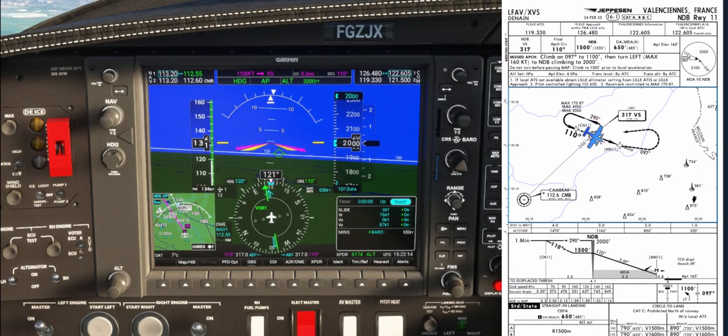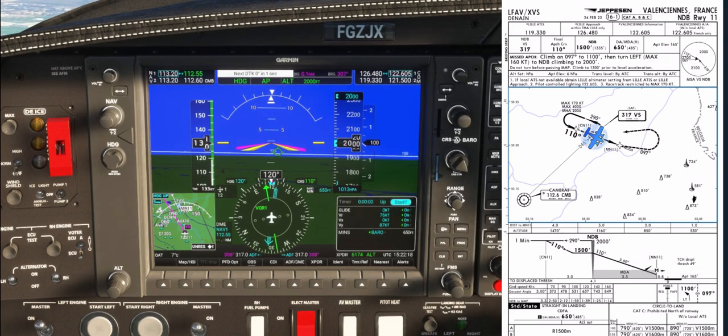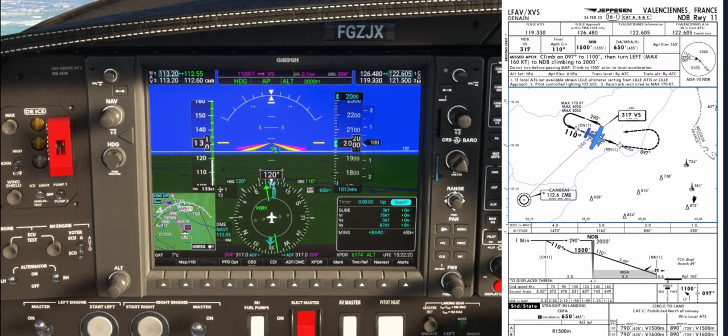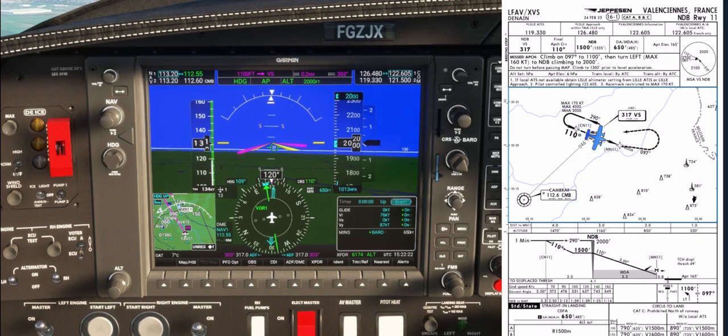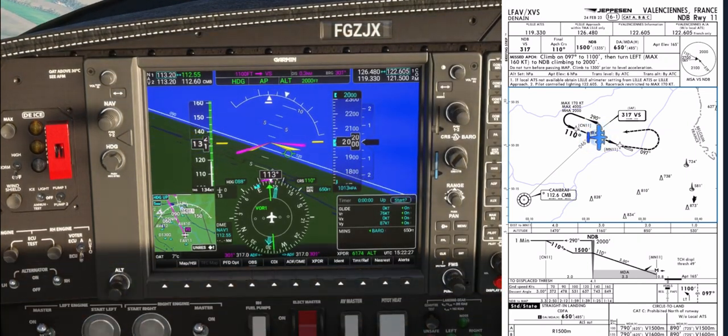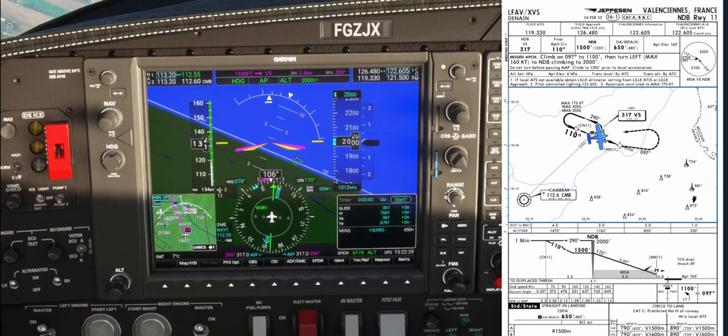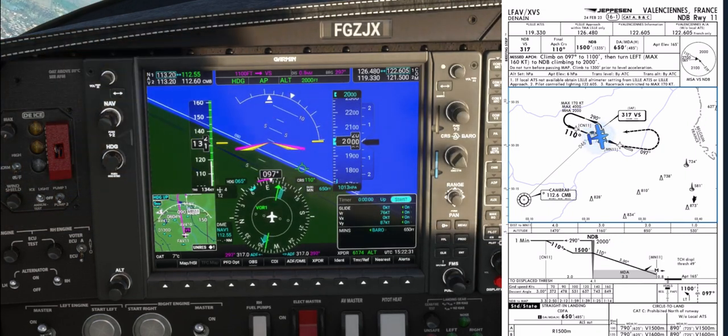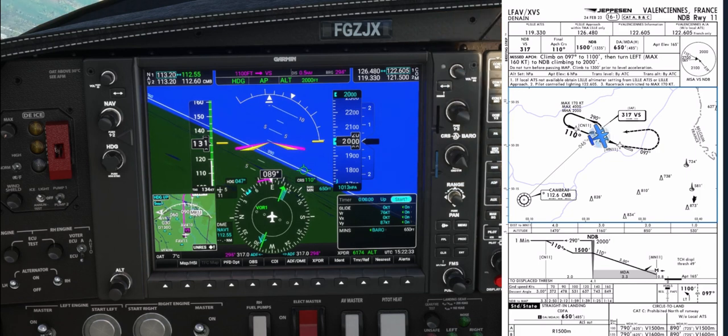Overhead the station, apply the next step you decided. Turn left to the outbound track 290 degrees corrected for the crosswind. Time, ready to start when crossing abeam the station. Twist, turn the heading bug. Talk, nothing to say. Throttle, check speed versus power and icing clues. Next step will be start the timer.